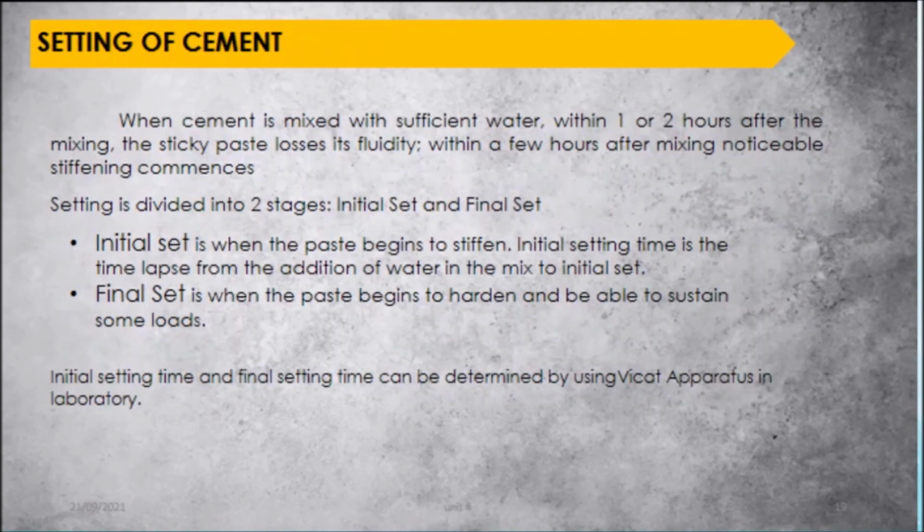So what do we mean by setting of cement? When cement is mixed with sufficient water, within 1 or 2 hours after the mixing, the sticky paste loses its fluidity. Within a few hours after mixing, noticeable stiffening commences. The setting is divided into 2 stages: first the initial set and then the final set. Initial set is when the paste begins to stiffen.